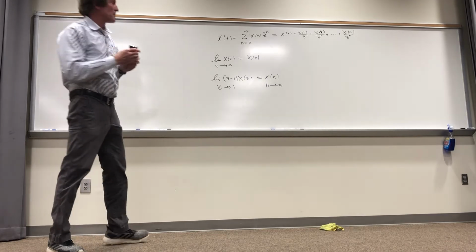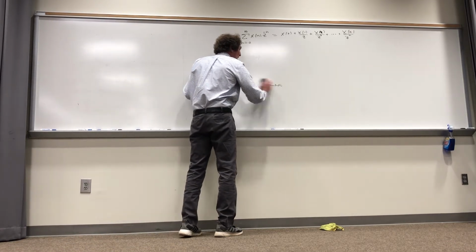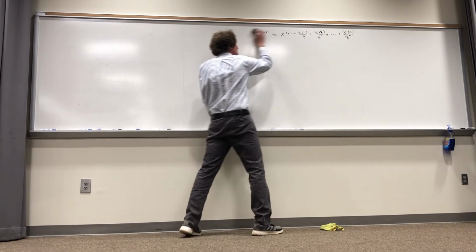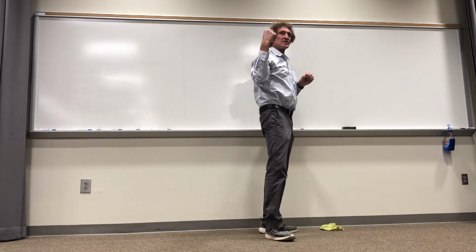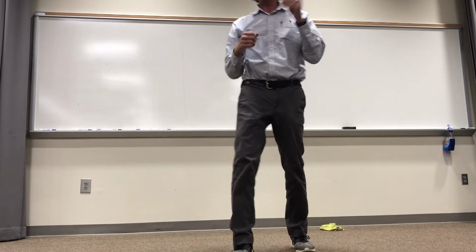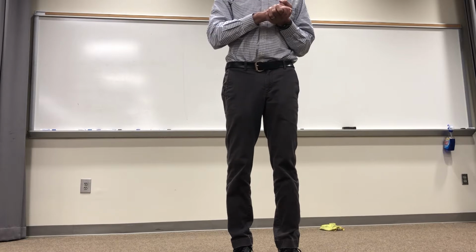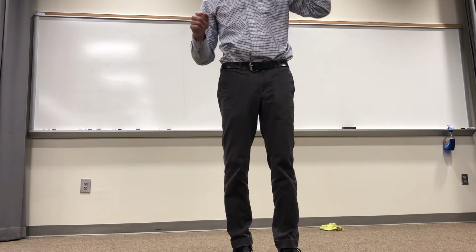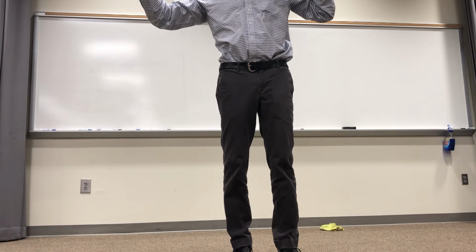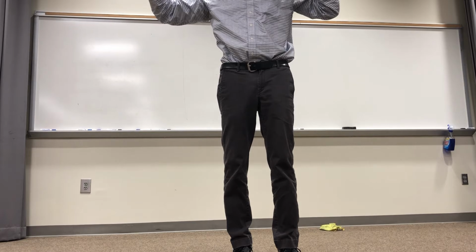You can think of any kind of differential equation solution as part of it having to do with the steady state, whatever the steady state input is that's exciting the differential equation, plus the response of the system to the initial conditions. For instance, on a capacitor and a resistor, if that capacitor had an initial voltage and there was an input-output and, say, a switch closed, then you know how to get the transient response, right?